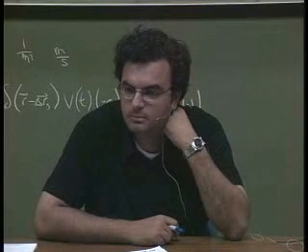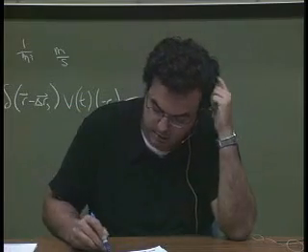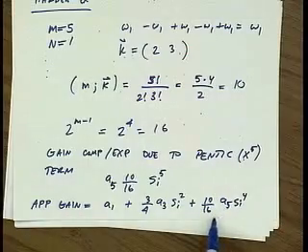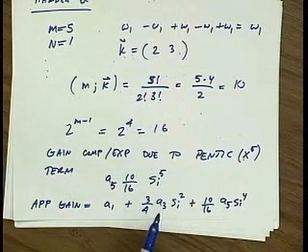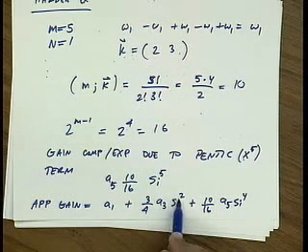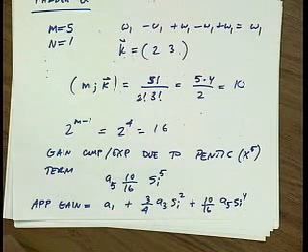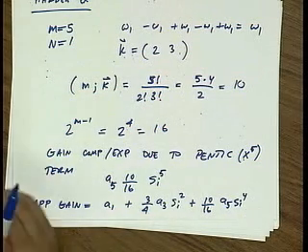How would you get a minus term in this if you were to get gain compression? So the sign of A3 and A5 are not known, right? They could be negative. Good point. You'll notice that once you know the sign, the gain compression or expansion is independent of the signal level because you're taking even powers.